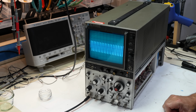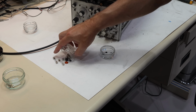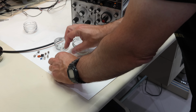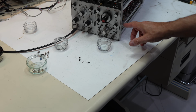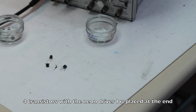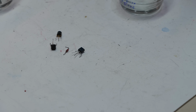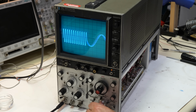Beautiful scope. I love this large screen, but man, was it difficult. I put it in the category extreme. Everything that was bad in the high voltage power supply. All this that was bad in the gate control. And then finally, in the timebase, not that bad. 3 transistors and a diode, but it was so hard to find because it was caused by a short that did all kind of horrible things to it. I tell you, the result is well worth it. But I just like to unfurl my little guy.